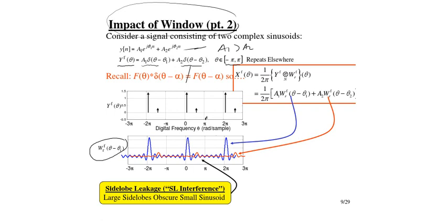So we have shifted it. Now we have to multiply these two operations. When we convolve these two, Y and W, what do we get? This is nothing but the delta, right? When we convolve with a delta, that function will be shifted to that particular position, right? The deltas are at particular alpha. So when we convolve any function with that, that function will be shifted to that alpha. So what will happen is, this sinc will go to these impulses.